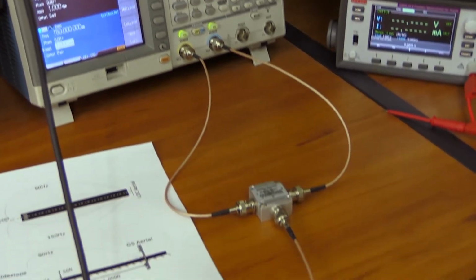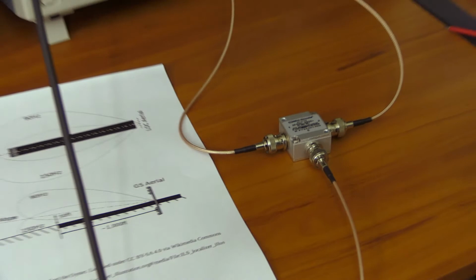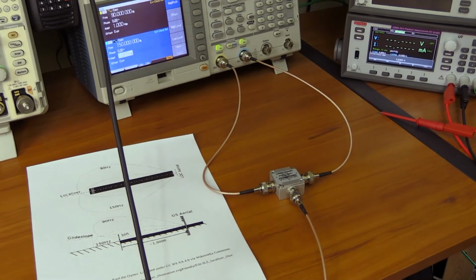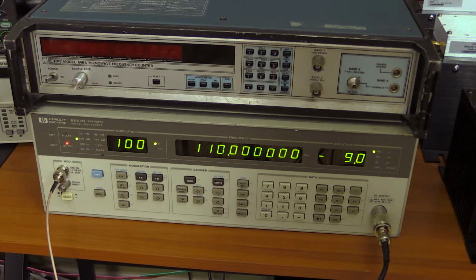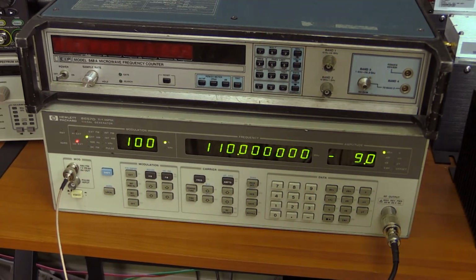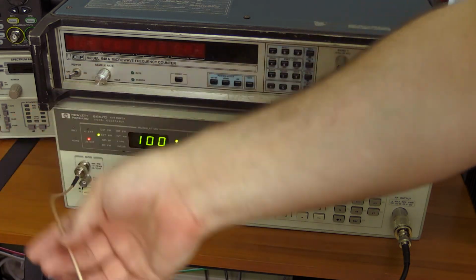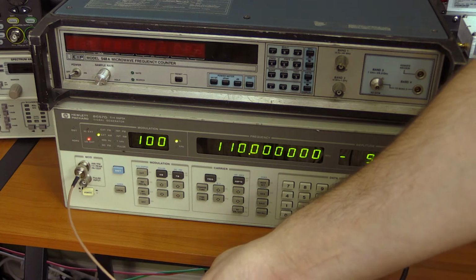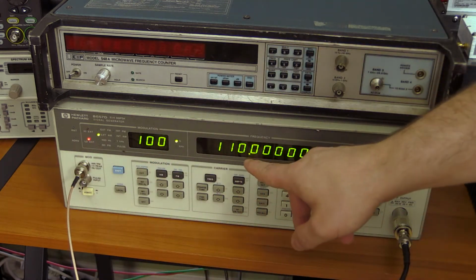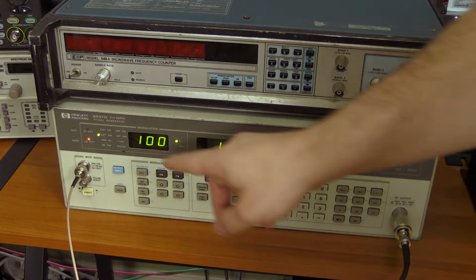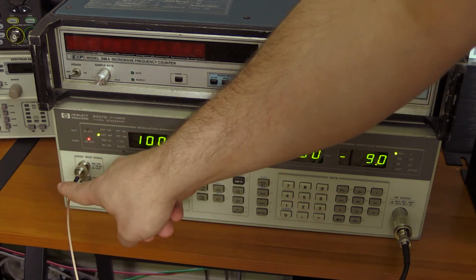Alright, next from there it goes into this Mini-Circuits resistive splitter that's used as a combiner to get both signals together. And from there I am going into my beautiful HP signal generator. You can see the settings here. This is from our splitter. This is the combined 90 Hz and 150 Hz signal input going straight in here. The box is tuned at 110 megahertz, -9 dBm. And we are amplitude modulated here through this external reference signal.